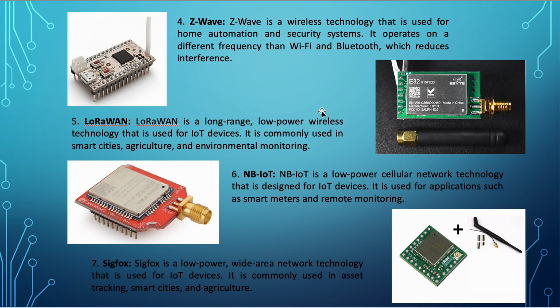When we have IoT devices, let's say moisture sensors are there too. We talked about moisture sensors and how we can use them, and now we know how to get data to a central location from the moisture sensor. We can use things like Sigfox or LoRaWAN to transfer that data long range, and we don't need much electricity.